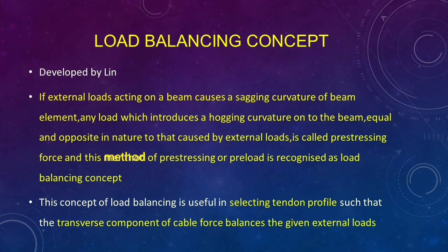Now the last concept is load balancing concept, which was developed by Lin. If the external loads acting on a beam causes a sagging curvature to the beam element, any load which introduces the hogging curvature onto the beam equal and opposite in nature to that caused by the external loads is called prestressing force, and this method of prestressing or preload is recognized as load balancing concept.